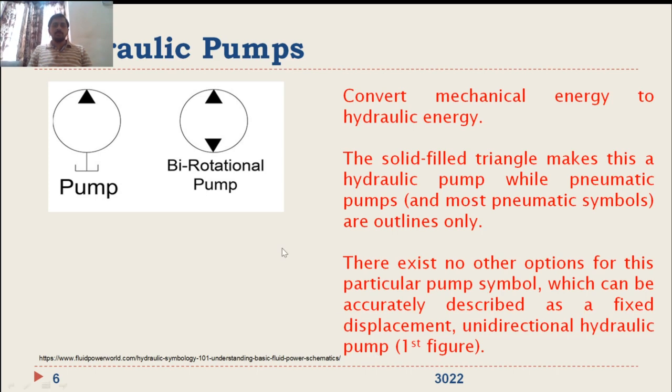Coming to the hydraulic pumps, you can have the energy converted from mechanical energy to hydraulic energy, right? The arrows used in hydraulic elements will be closely filled triangles. This means it uses liquid. In a pneumatic system, it will be openly filled, I mean there will not be any filling inside. It will be open arrows. So a solid filled triangle makes this a hydraulic pump.